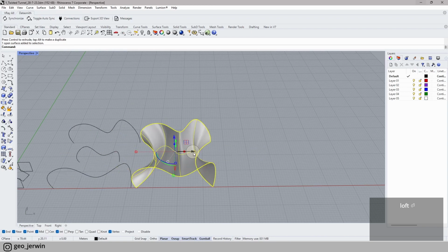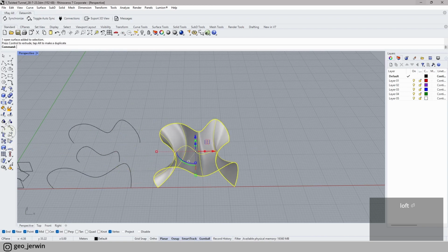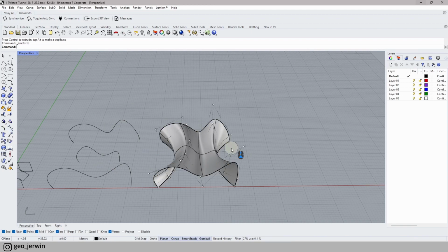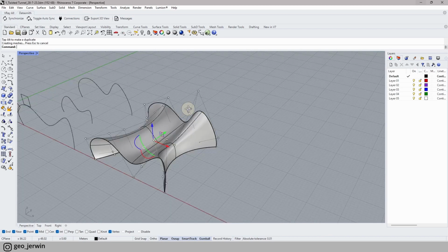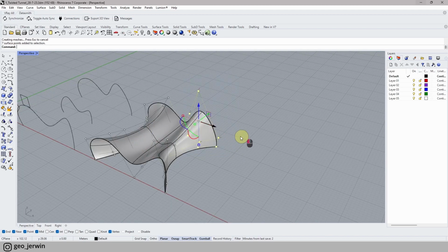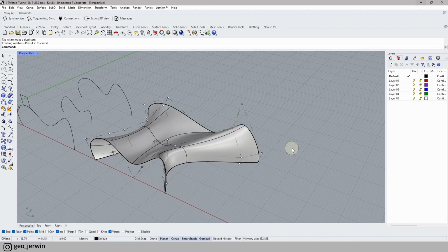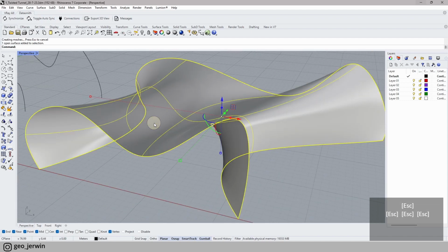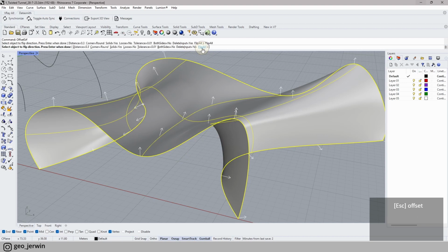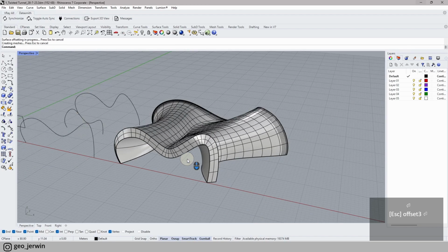And then if I want to control this surface, I can turn on control points, and then I'll be able to control this into different shapes. Right? That's basically loft. And if you want to create a surface thickness, you can just type OffsetSrf on the surface, and then you'll be able to flip to your desired direction and give a distance, let's say 3, and that's basically offset.